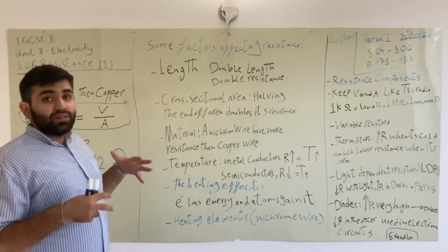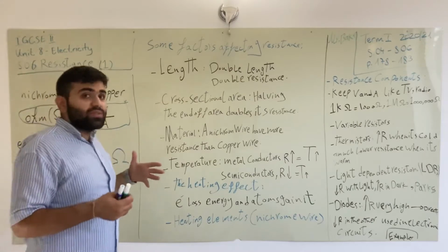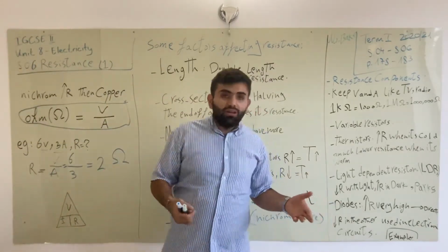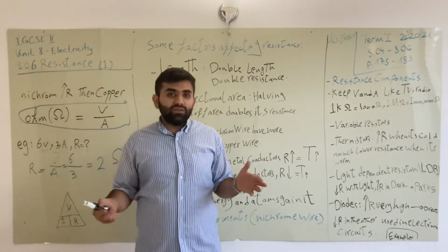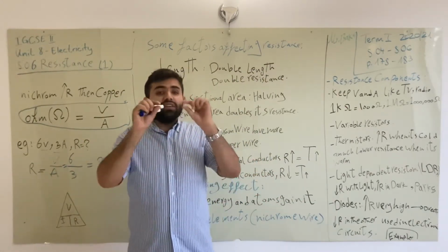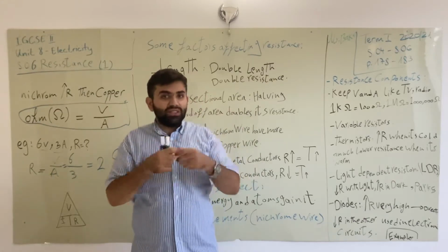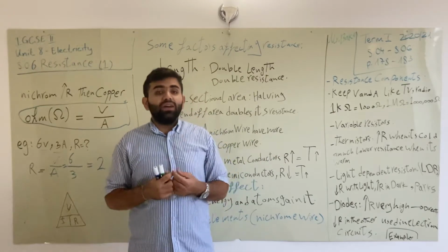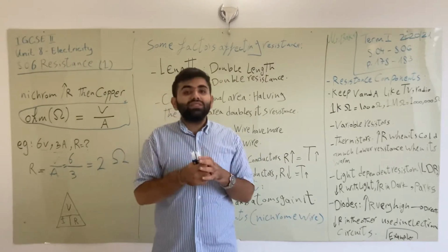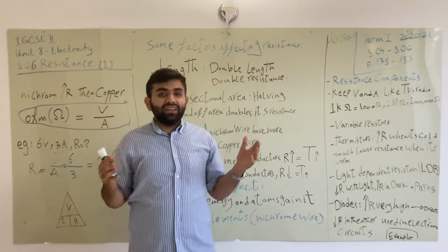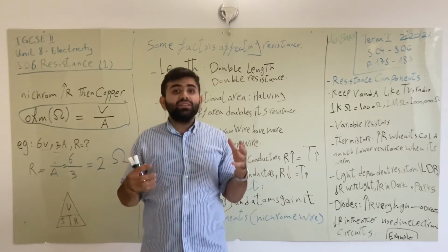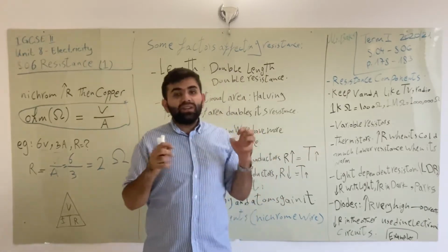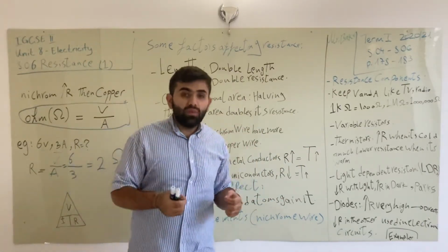So actually this is how we heat. This is how the hair dryer works, the toaster, the warmer, the oven, etc. Usually the filament or wire is made from nichrome. Why nichrome? It has very high resistance. That means more electrons are losing energy and the atoms vibrate more. That means they're gaining more heat.